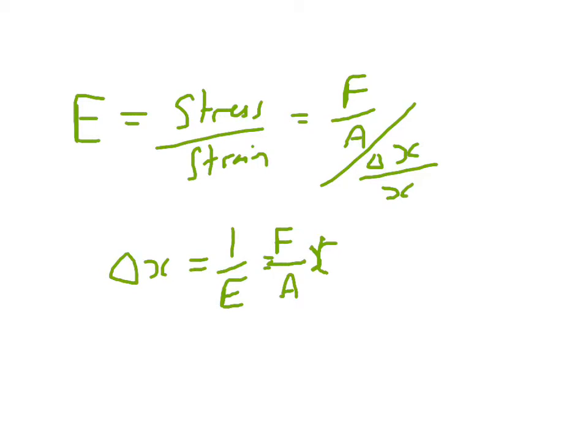If you have a go at the question on slide 6, that should be something you can already answer with the information you know. One thing I have had to point out in previous years is that a wire is a circular cross-section. But if you come back to this, I'll show you how to solve it. So you should have had a go at the tension in a piano wire question on slide 6 of the stress-strain lecture. With a 1.6 metre long steel piano wire with a diameter of 0.2 centimetres, you're looking for the tension in the wire if it stretches 0.25 centimetres.